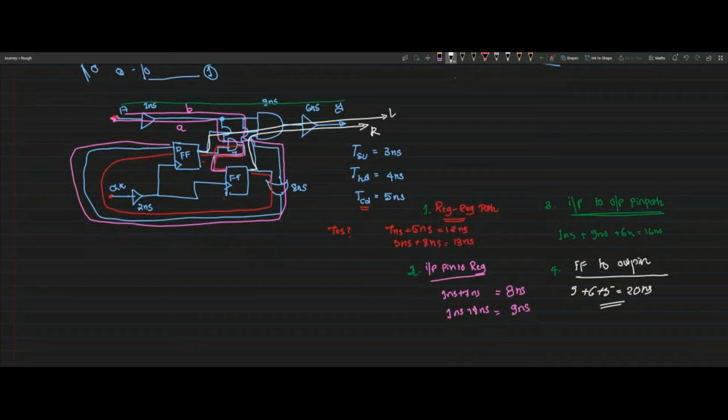And one more thing is also important. If you see there are some direct paths, this will create a lot of issues for timing analysis. It's a straightforward combinational path, and we don't know what input frequency data we get.